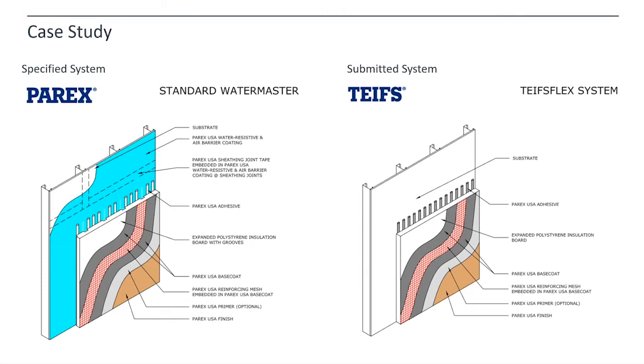The right system is a barrier system, but the left side has the secondary plane of drainage, which allows any water that penetrates through the EIFS coating system to drain behind that drainage pattern. Yes. But how does that affect what the code requires for each of these systems, and how is it different?